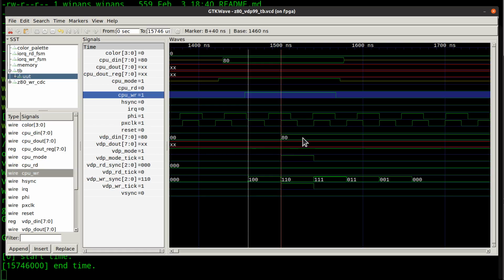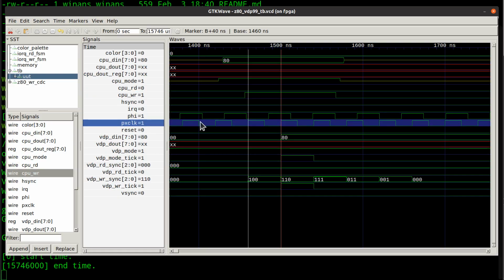and we will see that we need 2 full pixel clock periods to react if we use the synchronizer that I've designed here. And you can see that it actually, what is it doing? Oh, we're going to see I did a little bit of sloppiness in here, and I'm going to grab the data even after the one period. But we need 2 whole periods before we're golden.